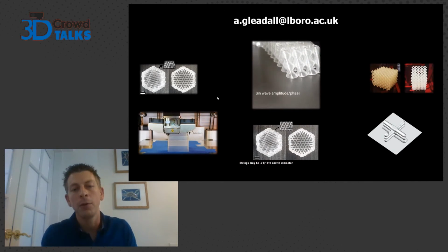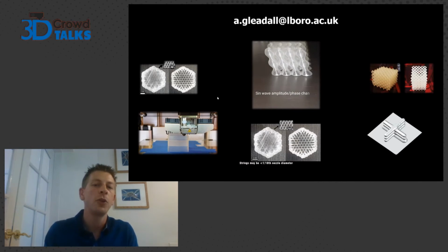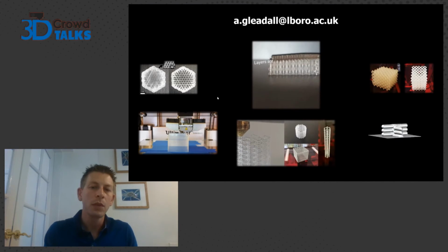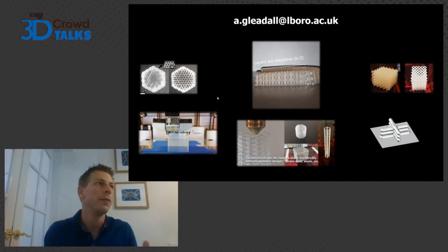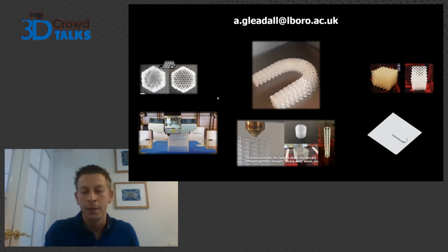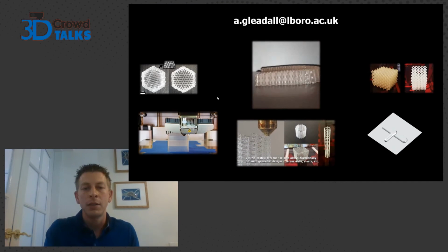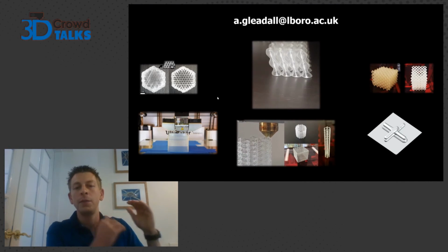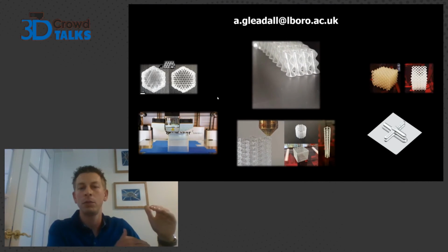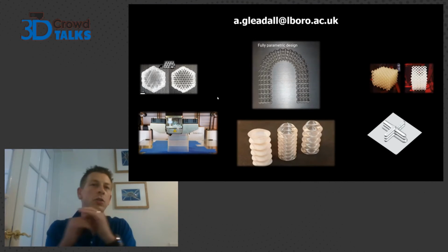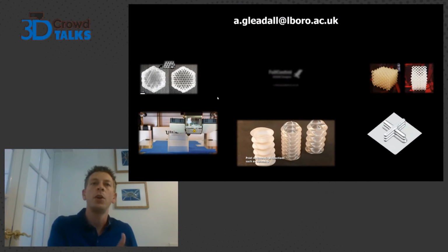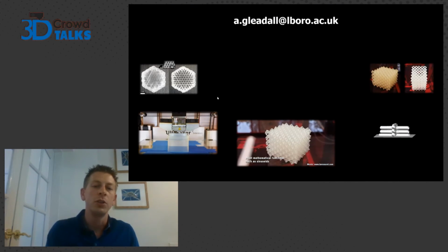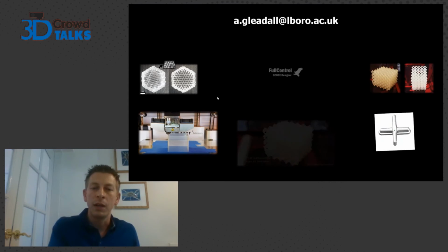I've programmed the software for maybe 10 or so printers at the moment, like Markforged, Raise3D, Prusas and things. Basically for each new printer, I'll take some existing G-code, identify the code at the beginning of the print, which is called the start G-code, and copy that across directly. Same for the code at the end of the print. The bit in the middle, which is the actual interesting structure, is the bit that we're really designing.